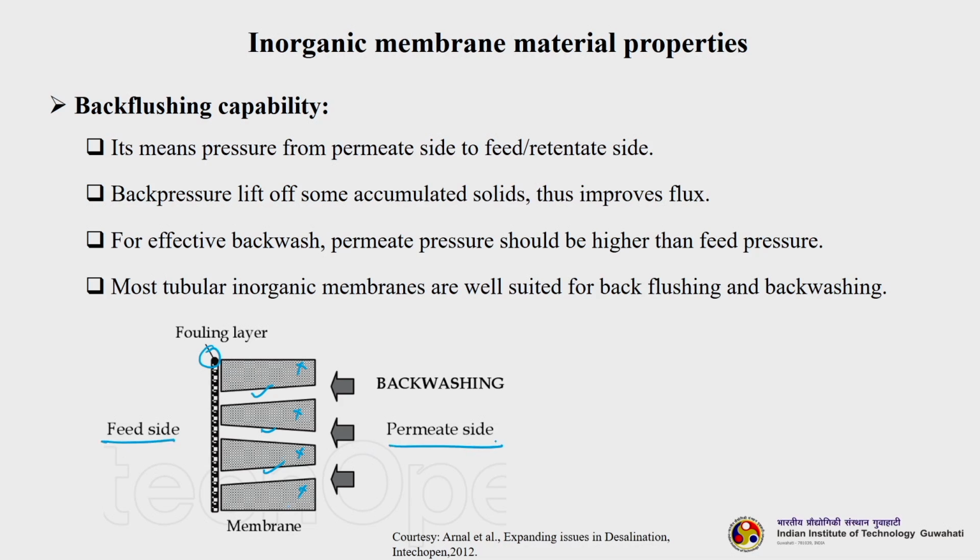When the process is getting carried out, feed is here, the solute will be separated, the separation takes place this way, and we get a permeate on the permeate side. When we are doing back flushing or back washing, the name itself indicates that we are washing from the back side of the membrane, feeding from the permeate side of the membrane.